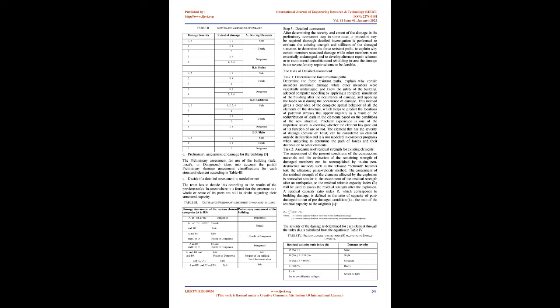First, classification of the severity of the damage. 1 none, 2 slight, 3 moderate to heavy, 4 severe to total. Joints, D 2.0 mm. Second, classification of the extent of the damage. Extent of damage refers to the number of elements with the particular damage severity marked.